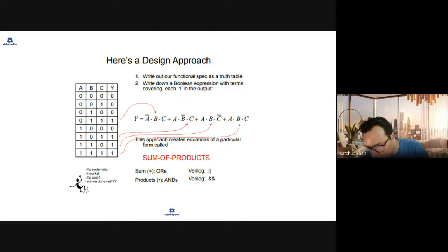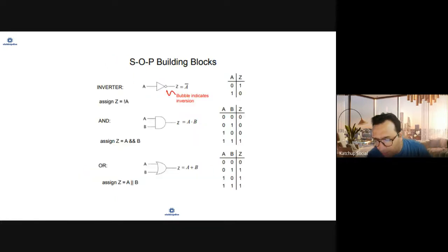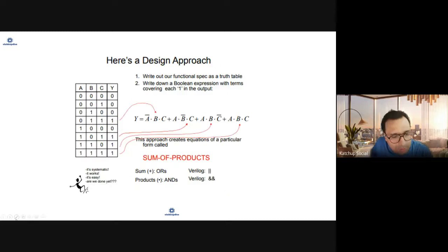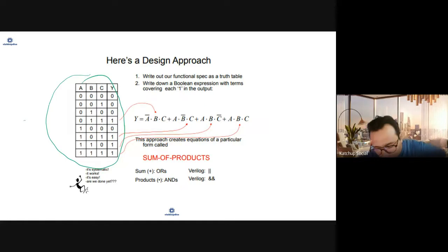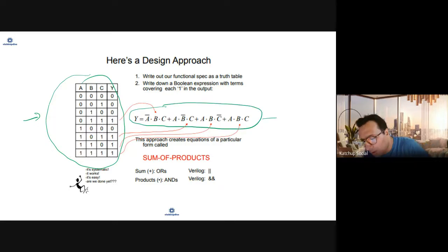So the first and foremost thing the synthesis tool does is convert your RTL into a Boolean representation. So this is basically the same RTL representation in picture format, or what is known as a Karnaugh map, or it will convert that into a Boolean table or Boolean equation inside the tool.